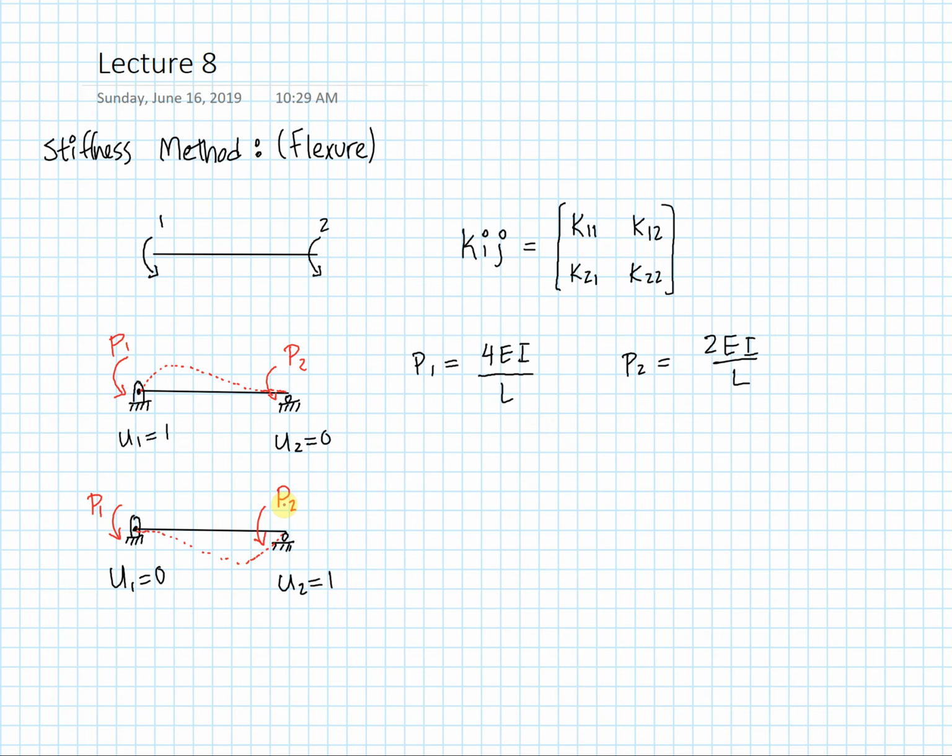And when we formulate the local and global stiffness matrices, we need to continue on with this sign convention. Otherwise, things can easily go wrong, our calculations will be incorrect, forces will cancel each other out, and it will look ugly. So it's very important to maintain whatever orientation you formulate your matrices with.